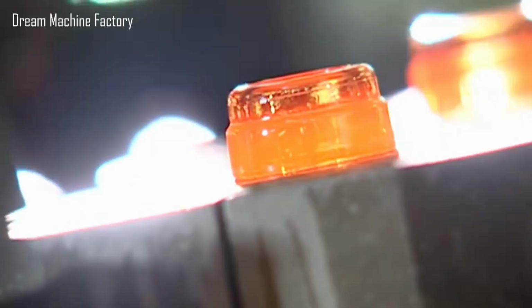There are two main forming methods: blow and blow. Compressed air first forms a cavity in the gob, creating a partially shaped container. The piece is then transferred to a blow mold, where compressed air again shapes it into its final form. Press and blow. A metal plunger presses the initial cavity in the blank mold, followed by compressed air shaping the container in the blow mold.